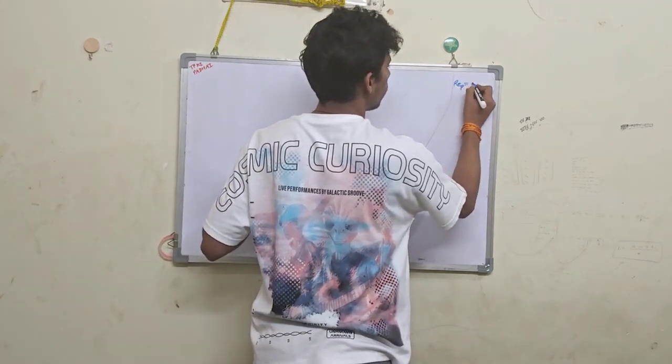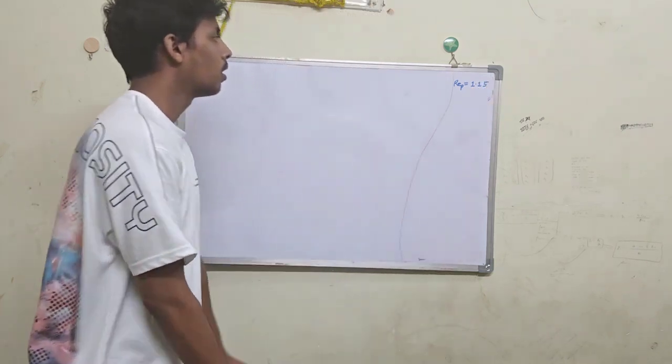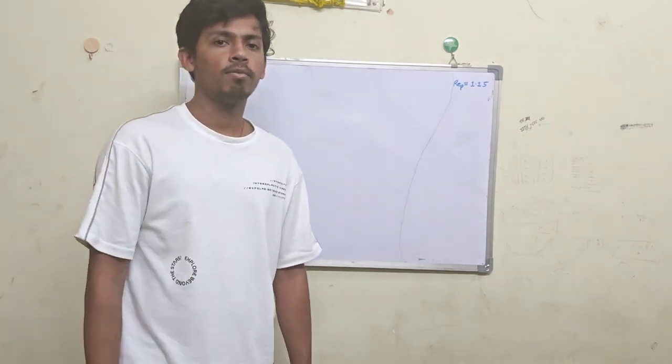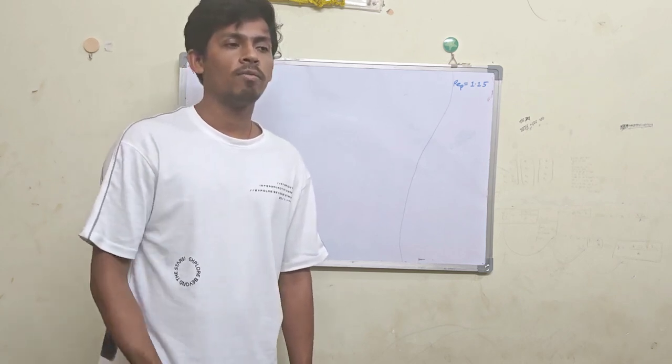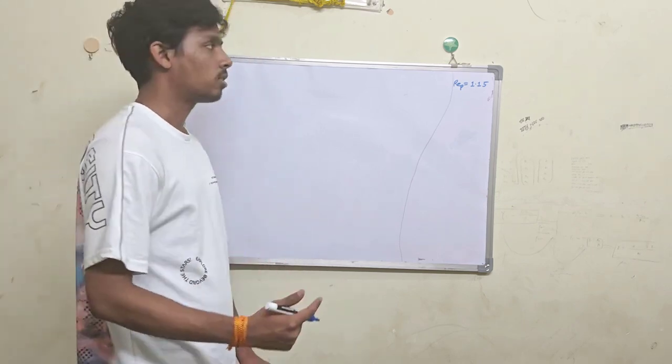Reynolds number came out to be 1.15. Now in calculating heat transfer in a packed bed, we have written the formula of Chilton-Colburn factor for heat transfer. Here we will write the Chilton-Colburn factor for mass transfer.